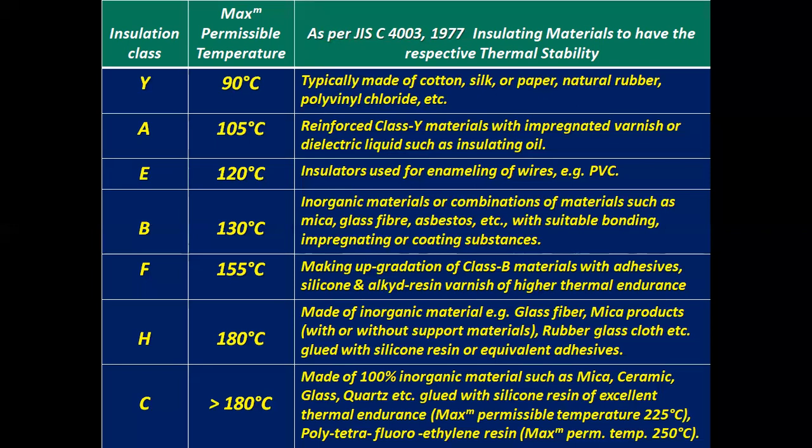Class C, which is greater than 180 degrees centigrade, made of 100% inorganic material such as mica, ceramic, glass, quartz, etc., glued with silicone resin of excellent thermal endurance, maximum permissible temperature 225 degrees centigrade; polytetrafluoroethylene resin, maximum permissible temperature 250 degrees centigrade.